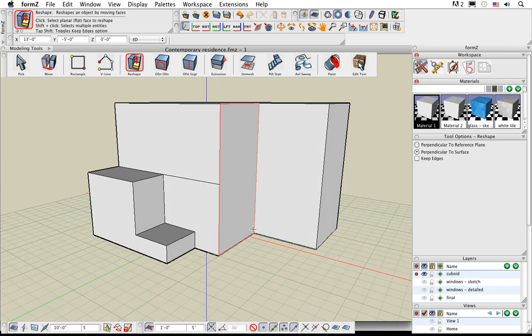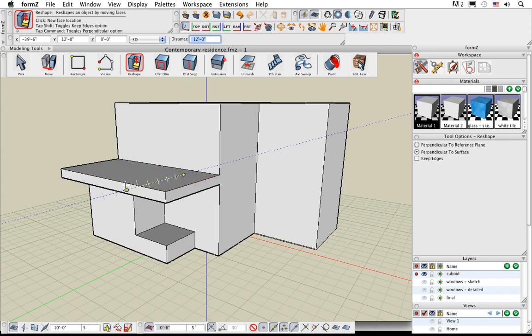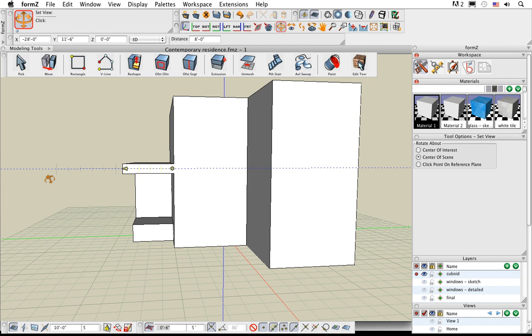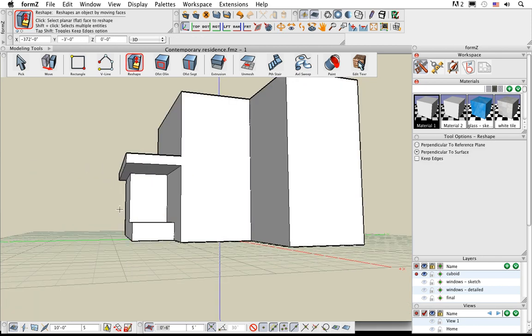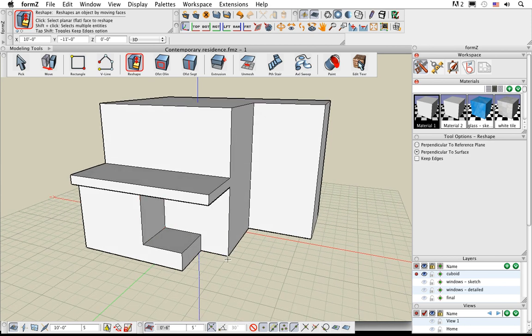All right, now at this point, let's create some kind of a roof or overhang over the vestibule. And so I'll use the Offset Segment tool again, and I'm going to reduce my grid snap down just a little bit, maybe make that 6 inches. So I'll take this existing edge that's already there, offset that, and then reshape that to create the nice little overhang. Now also notice that if I snap right to that existing face, the reshape operation is a real-time Boolean function, so it is healing that geometry and resolving the true solid nature of that solid object. But in this case, I want to actually have a little overhang there, so I'm going to swing to a side view here and just extend that as far as I want, maybe something like that. Okay, we have a nice little overhang for the roof over the front entrance of our space.